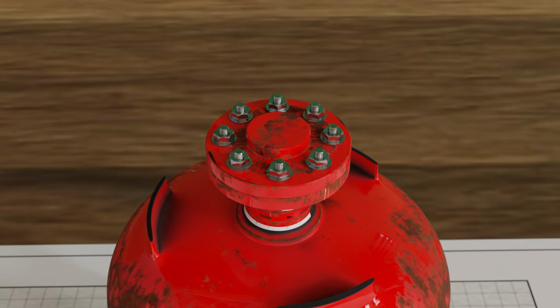Even if the bolts can withstand the pressure in the vessel without permanent deformation, they will still deform elastically. If the bolts stretch too much in the process, the clamping force between the lid and the vessel decreases, and sealing may no longer be guaranteed. In this case, therefore, not only strength limits but also deformation limits must be adhered to.